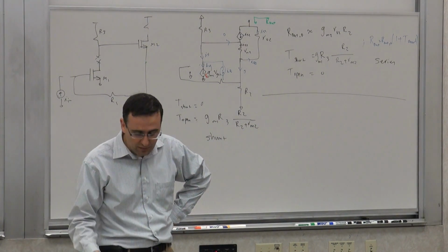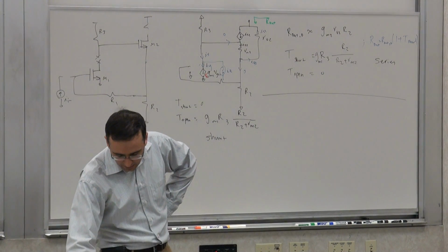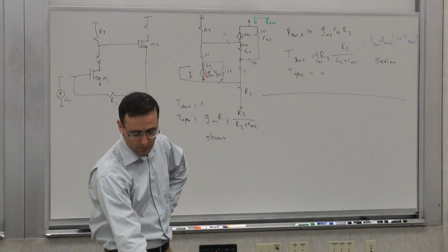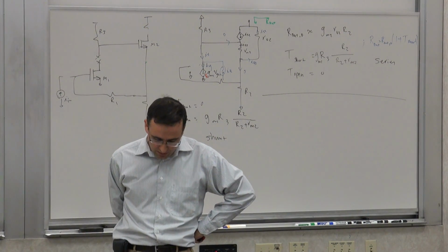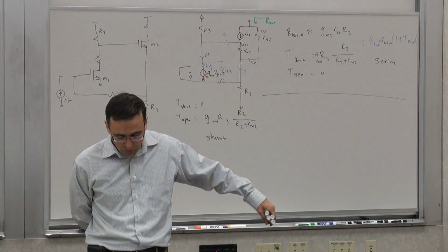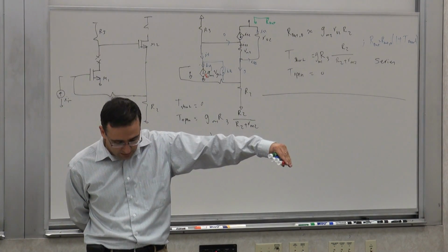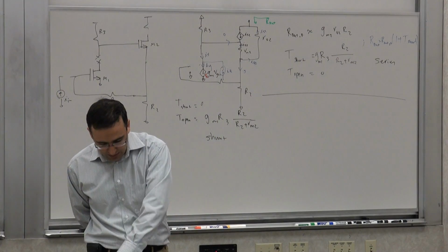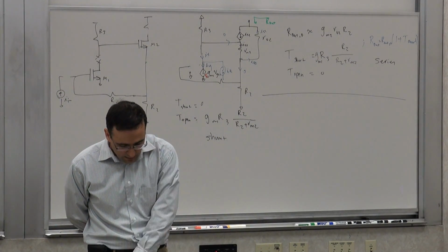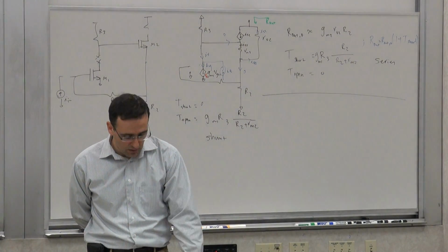And then, just to make it more interesting, we added the CGSs and CGDs for the transistors. If you look at the SPICE simulations, of course you start at low frequency with a constant impedance. Then the impedance drops, you have a couple of poles, then you see a zero, and then a pole. You can basically see what the behavior looks like.